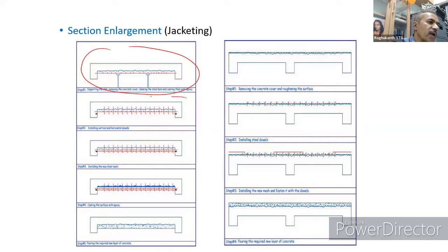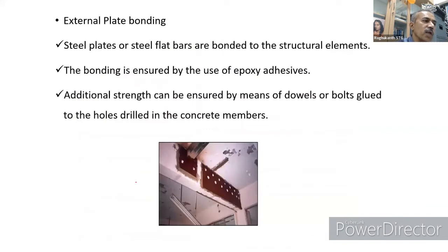So automatically you can find how to handle the vertical load, this becomes very straightforward. There were some places where you can put some steel bars, like passive strengthening, for the slab or for the beam, and bonding epoxy adhesives for additional strength. This we have recommended, and we have found out the causes also. Mostly the cause is chloride induced corrosion.